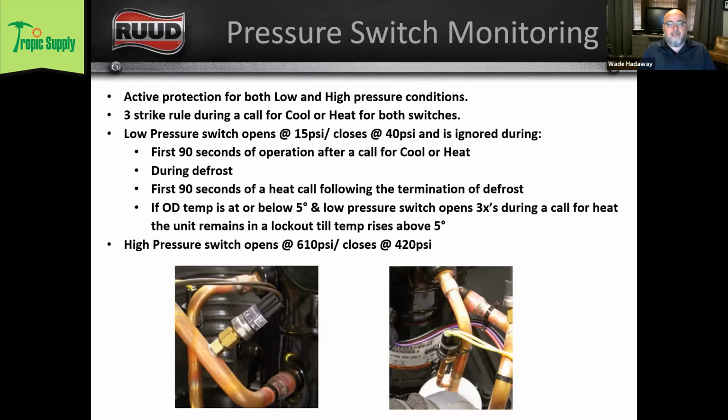You guys are probably not going to see that in the climates in Florida, but as heat pumps become more and more prolific and more efficient, that footprint for heat pumps moves further and further north, and the colder it is outside, the lower that pressure is going to get. I wouldn't expect that we're going to see anything even close to that anywhere in the southeast, but that's why we don't want to see any nuisance low pressure trips when there's not really a problem. It's just because it's extremely cold outside. I hope that answers your question. Yes, thank you.